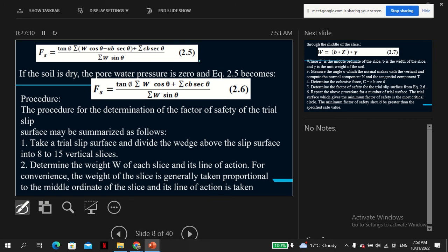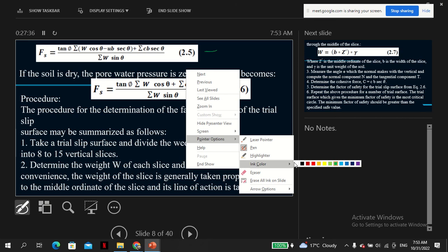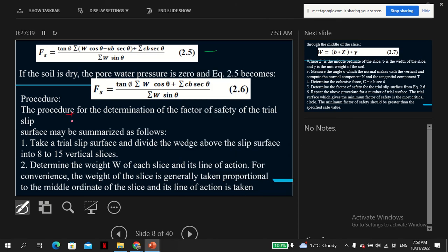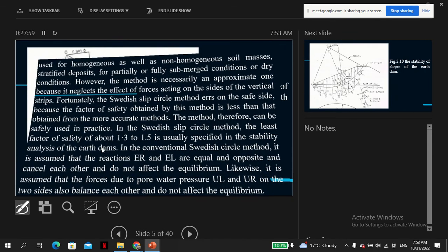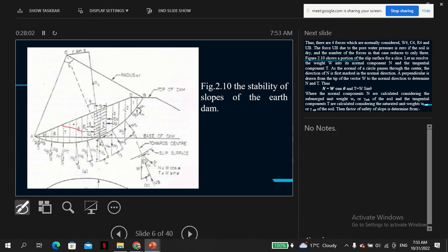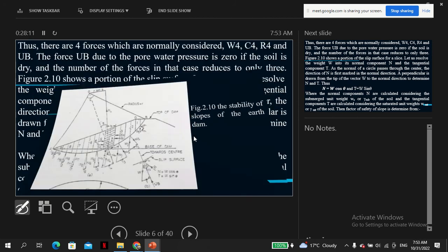So you know the shear strength of the soil is C plus sigma tan phi. So this is the phi we are talking about. Now theta is the orientation, theta is this. This has a slope somewhere, so this is the theta. So don't confuse those two things.